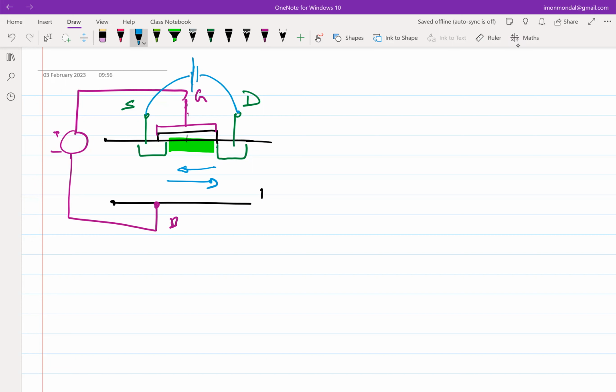Note that if you had some preliminary introduction to BJTs in ESC 201, in a BJT, you cannot do this. It's basically the structure of a BJT is as is. If you reverse the collector and the emitter, you can as well mark one as emitter and the other as a collector, but the BJT will not work. But in a MOSFET device, it really doesn't matter. Your source and drains are interchangeable, and how is it interchangeable? The one that is at a higher potential is the drain, the one that is at lower potential is the source in this particular type of MOSFET. Okay.